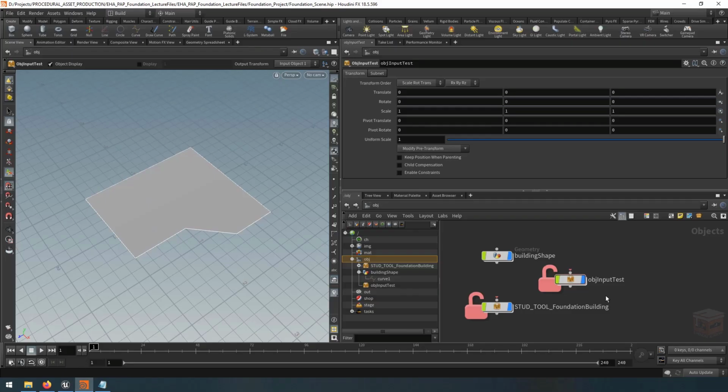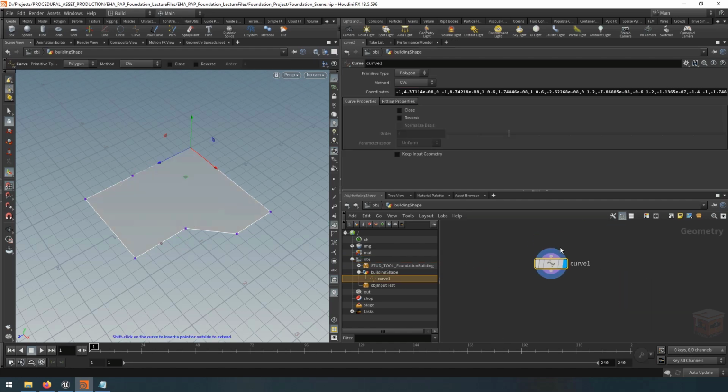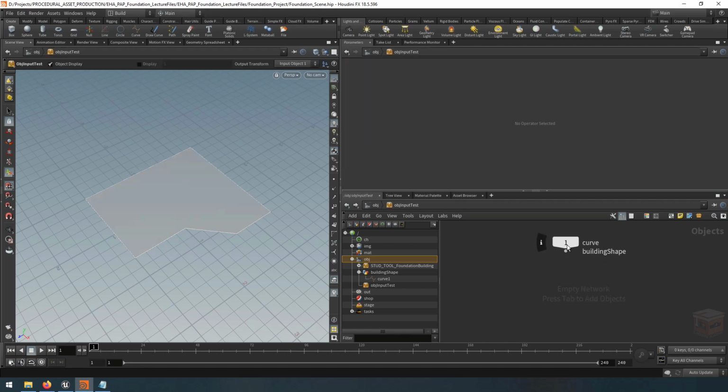Let's go back to Houdini, and in here let's go to this object input test. Let's try to plug in our curves. So here we have our curves, right? They're inside this container. Let's plug them in. So if this was the SOP level context, then now you would think you would have these curves go through this line into our object level asset. Okay, so let's go with that. Let's go inside, and here we have our input. Okay, so next, what do we do?